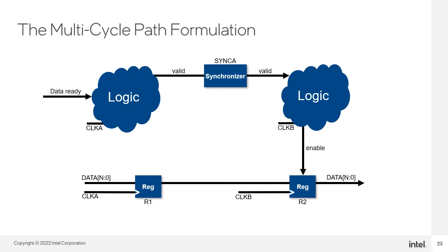You can make this circuitry even more robust by creating an acknowledge signal synchronizing from clock domain B to clock domain A. With this setup, there is one bit that is going through a synchronization process, which is the enable line for the bus data. Since the enable line goes through multiple registers and therefore multiple clock cycles before it reaches R2, the bus data will have had multiple clock cycles as it travels from R1 to R2, pushing more of the potential metastability issues on a single bit rather than an entire bus.